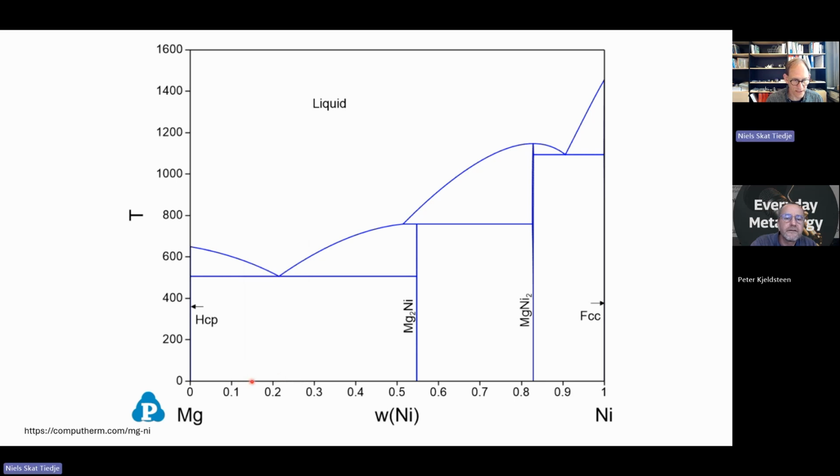We are with the 15% located here. And that means if I go up in temperature, and what the structure we saw started somewhere at a high temperature, then the phase diagram will show me at different points in temperature and mixture what structures we get.